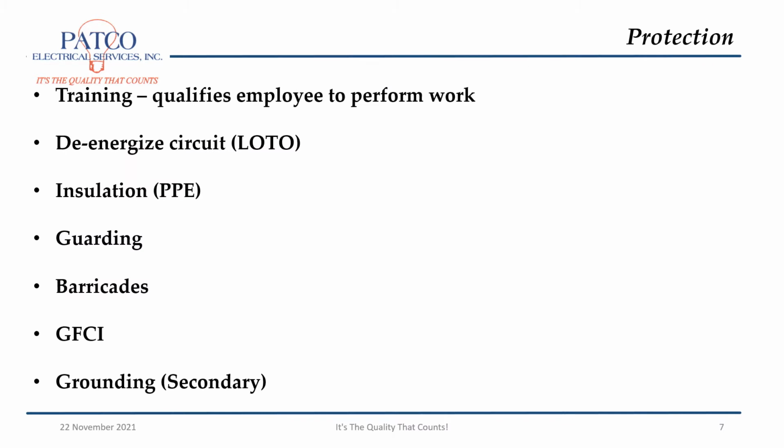Protection, of course: training, which qualifies employees to perform the work; de-energized circuit, lockout tagout, some type of insulation, PPE. Just because you have PPE on doesn't give you the excuse to go in there and work live. Always try to turn it off before we have to justify energized work. Also guarding, barricades, ground fault circuit interrupters, and grounding secondary.